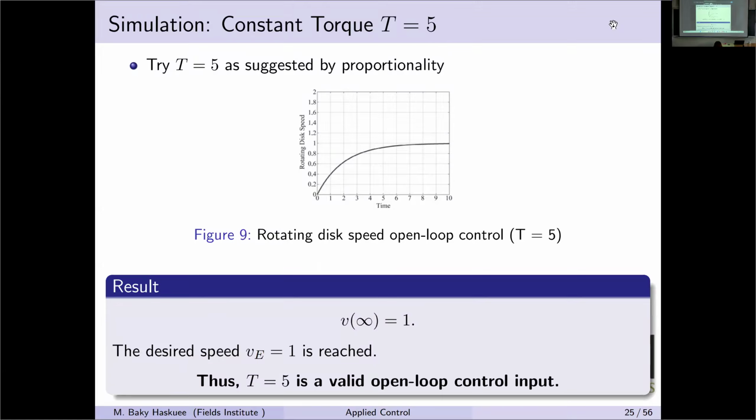So if I set this equal to 5 and this constant, then I will be determined, and I will set the torque. So the velocity of the disk actually depends on T. If T is equal to 5, this is the optimal level. So I should set the voltage such that I have T equal to 5, based on this equation. Given that I have the resistance, what voltage do I need to set such that T is equal to 5 given Tm? So this is set by the controller, and this needs my information.